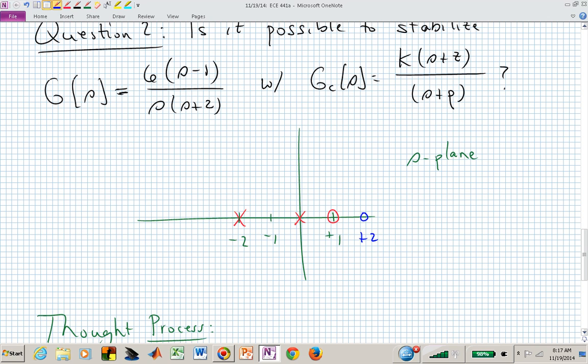but you have to build this. So go tell your boss you need to put a pole at infinity, and they're going to say, well, we can't even communicate with things on that asteroid. So infinity, yes, that's the right thinking. And what you would say then is, well, what is infinity? It's sort of like this infinity of time. It may not have to be that far into the left half plane. Like our 5 time constants is like infinity. Let's say that we put a pole right here at -4.